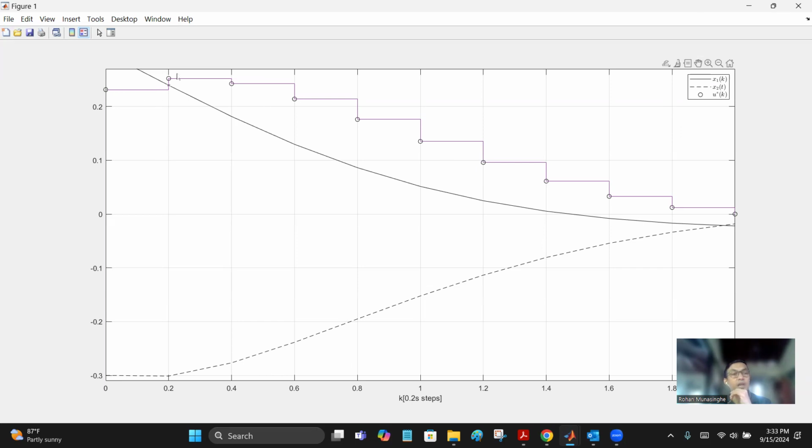This is the discrete time control sequence, right? This is actually the optimal control sequence. There is no other control sequence which gives you this regulation process, because you can see both the state variables x1 and x2 go to 0, right? Somewhere over here. They're still not there actually, right? There's a little further to go. But anyway, you know that you are actually heading in that direction, even though you are still not there. Okay. And this is the control sequence which gives you the minimum cost.